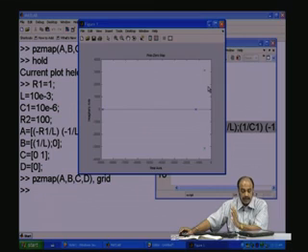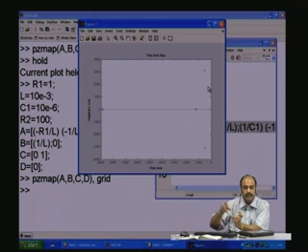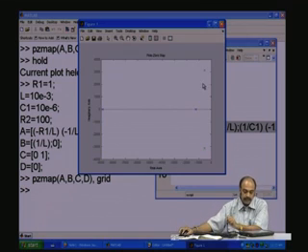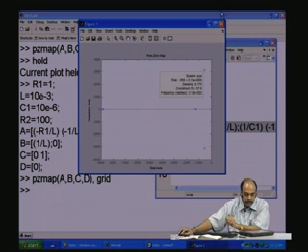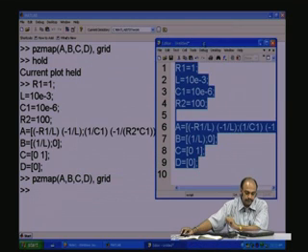So, you see that this phenomenon which is exhibited in the time domain gets reflected. The same phenomenon can be viewed in different ways in the frequency domain and the pole-zero plots, and this will give you exactly what you want to do for design, if I want to place the poles at any specific points for specific circuits for specific applications.